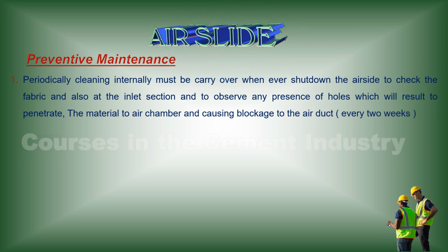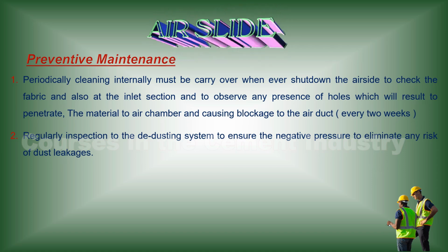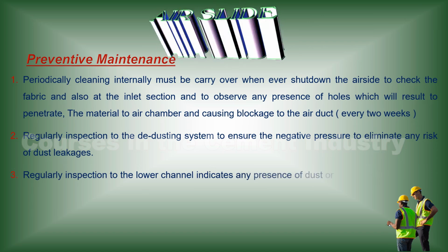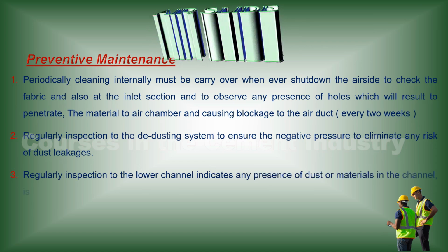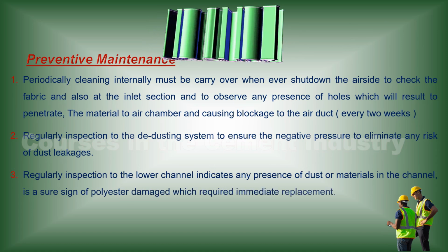2. Regularly inspect the dedusting system, to ensure the negative pressure to eliminate any risk of dust leakages. 3. Regularly inspect the lower channel. Any presence of dust or materials in the channel is a sure sign of polyester damage, which requires immediate replacement.